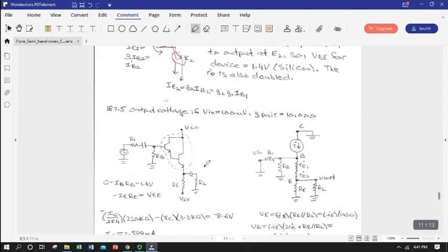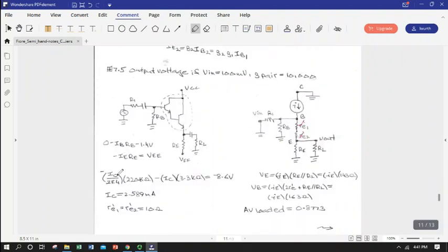We can treat that pair as if it's just a single BJT. So you can step through example 7.5, and you can see here on our AC model we basically have two r little e's, and when we calculate our collector current, instead of a 0.7 base emitter drop, we've got a 0.7 plus a 0.7 drop. So that's the effect of the pair seen.